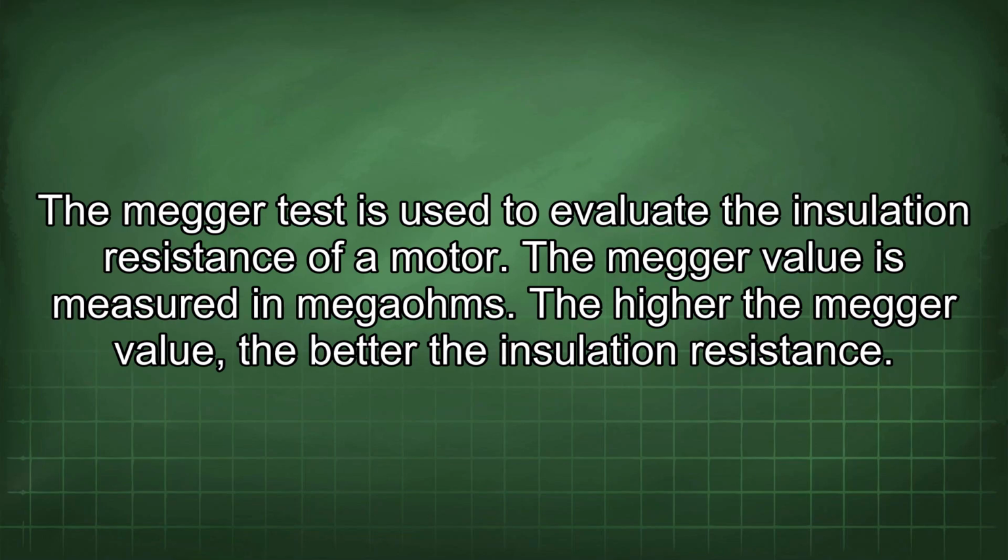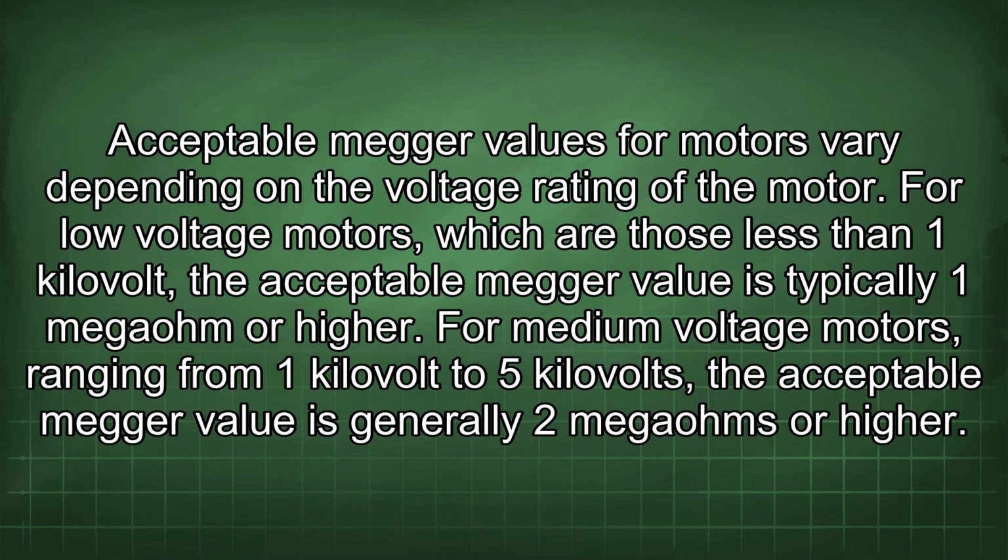Megger test is used to evaluate the insulation resistance of a motor. The Megger value is measured in megohms. The higher the Megger value, the better the insulation resistance. Acceptable Megger values for motors vary depending on the voltage rating of the motor.